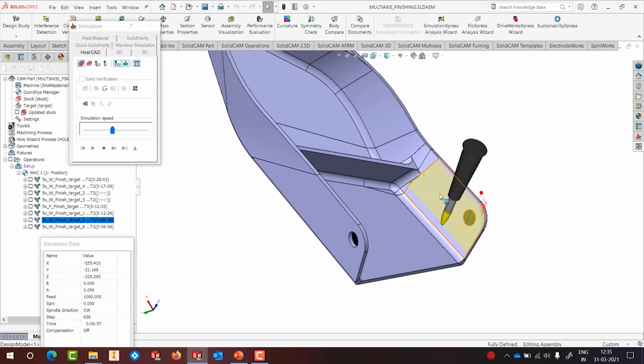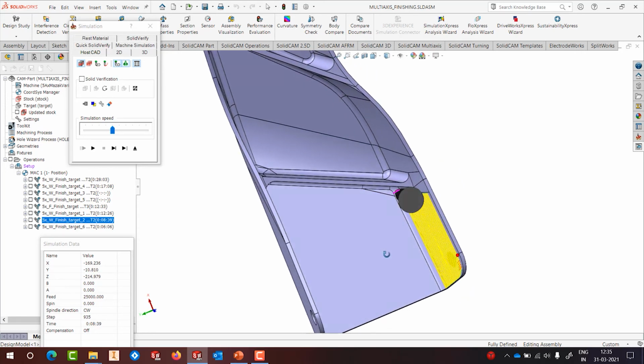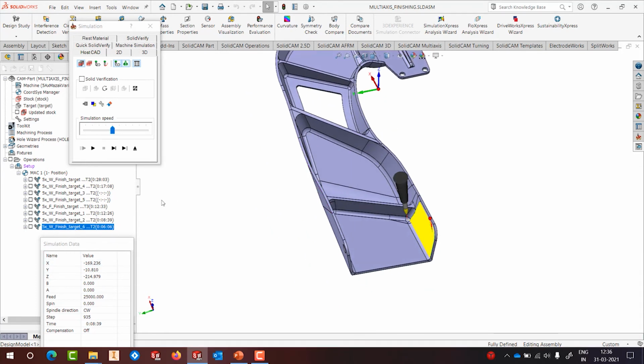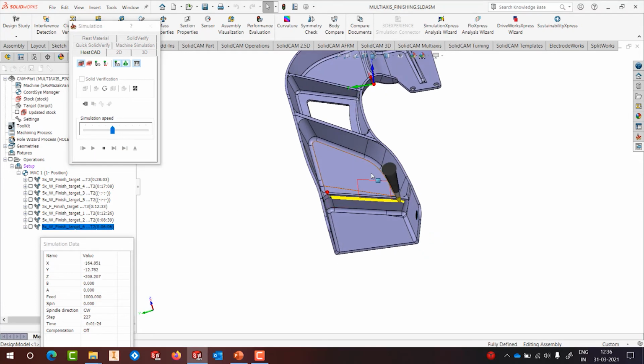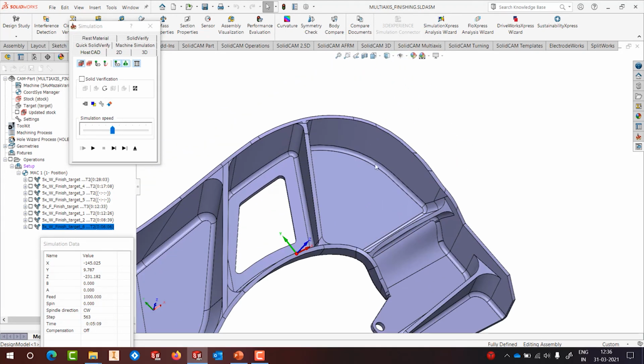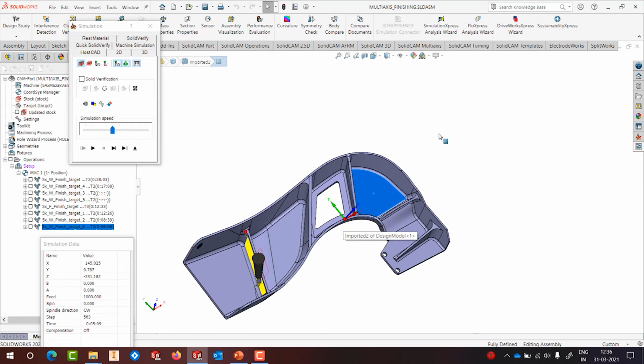We simply have to define the floor, wall, and the machining surface, and everything else is handled by SolidCAM. And the one in the center, that also can be done. Completely checked for collisions. Now with the automated stuff, we could also machine floor geometries where we just define the wall and the floor and the machining surfaces, and the floor is automatically done.